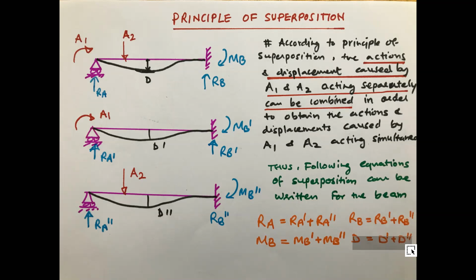This you have to keep in mind, because when you go for higher studies and learn some advanced courses where the word non-linear is used, what do you mean by non-linear? The force and deformation may not be related linearly, because in some situations you apply the force, but deformations are very, very large, in some other form, say exponential, or it happens because flexible structures have that. In another situation, the forces are larger and the deflections are very small, in the case of concentrated loads and impact loading.